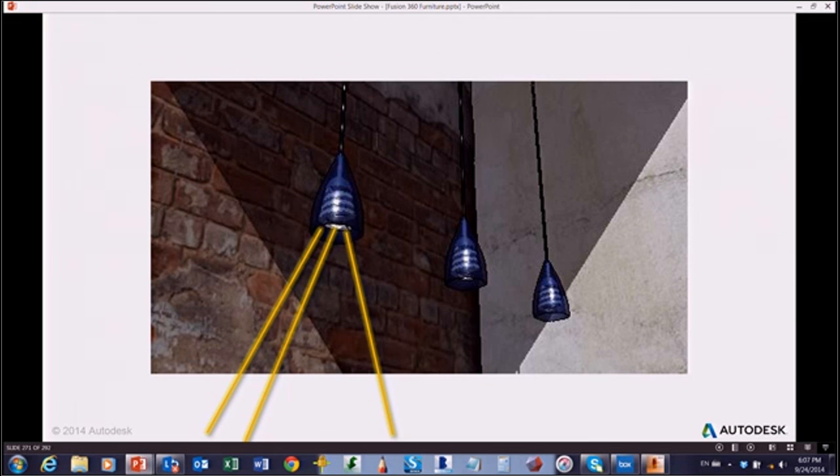Could you make that geometry 90% or 10% opaque? Not with that light source. The light source in the family needs to be below. Sometimes I'll put it a couple inches below. It's just the result in the room. You don't want that to shine through any materials. The light bulb can. That can be self-illuminating, and that gives you the effect you want of it glowing. But that's tricky. When you do those families, there's two separate things: the light result in the room and the actual little light bulb.